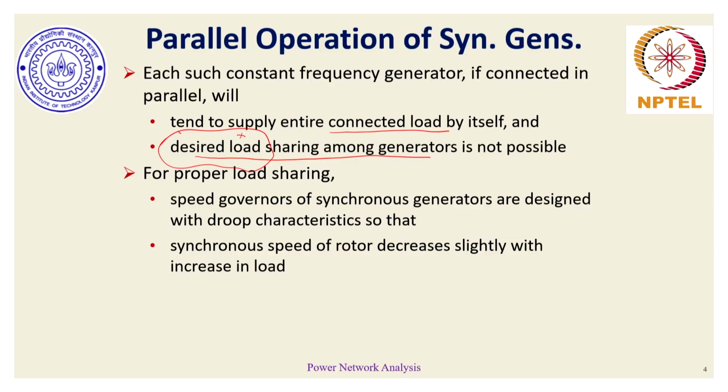So that's where this notion of speed governors comes in. For proper load sharing, our synchronous generators are equipped with a special device known as a speed governor, which keeps track of the load which is being taken up by the generator and the synchronous speed at which the rotor is rotating.